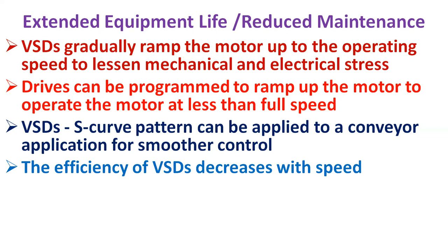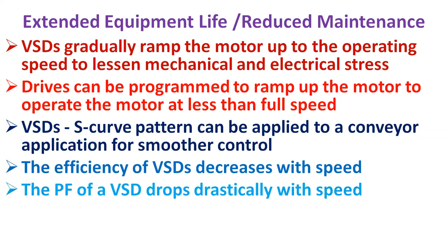Variable speed drives can also run a motor in specialized patterns to further minimize mechanical and electrical stress. For example, an S-curve pattern can be applied to a conveyor application for smoother control, which reduces the backlash that can occur when a conveyor is accelerating or retarding.